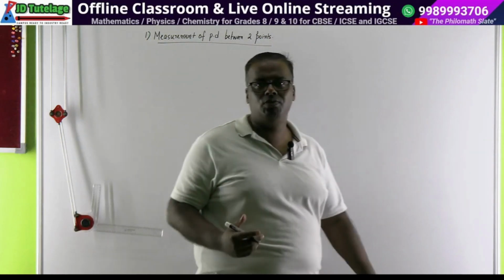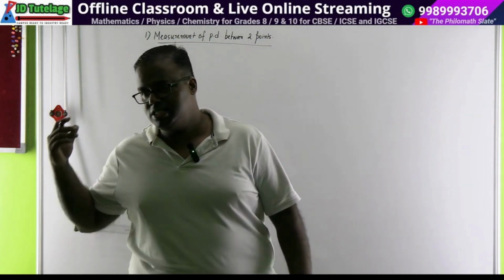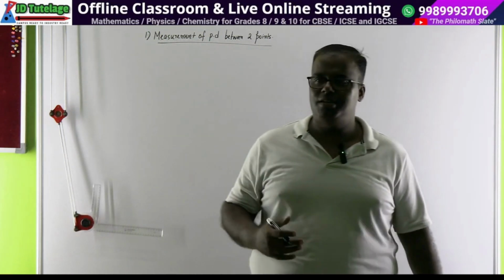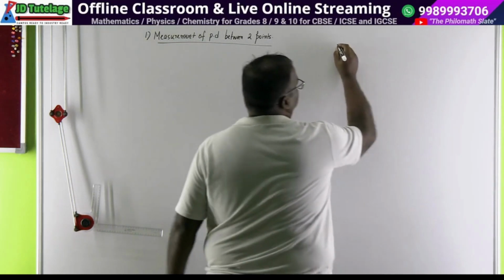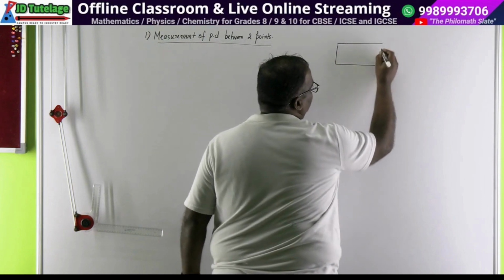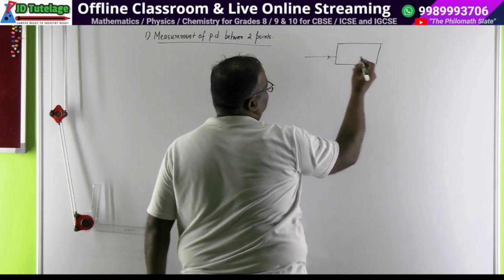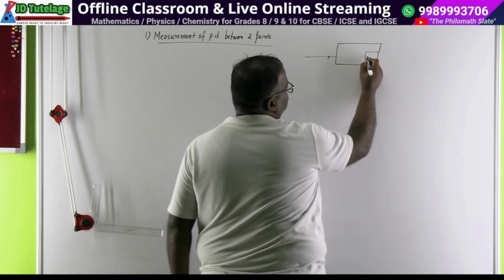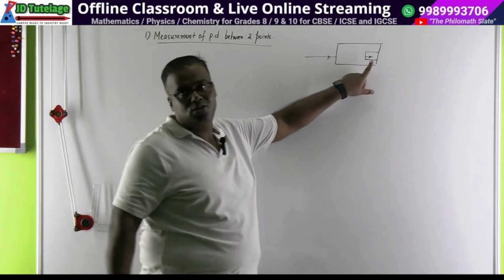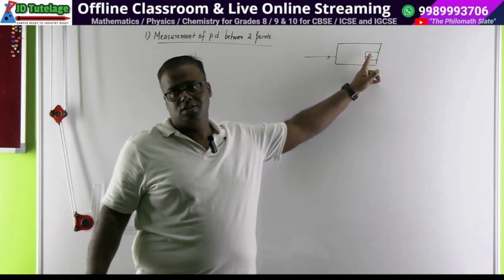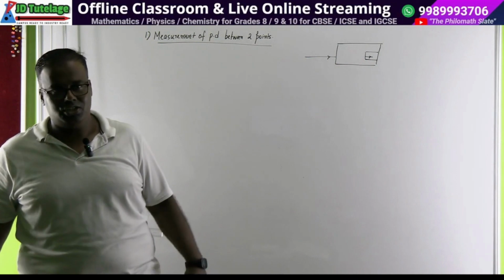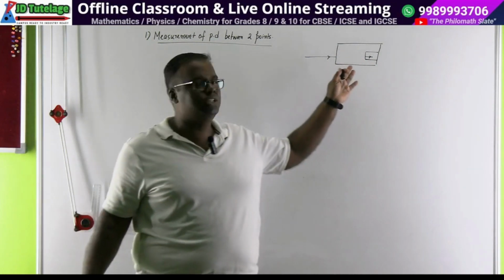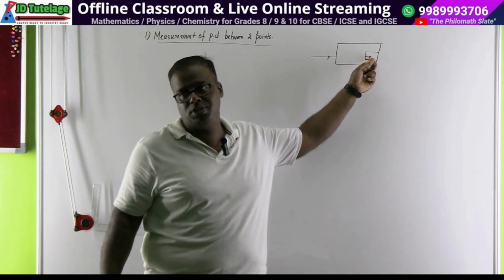If you are a little bit familiar with plumbing, basics of plumbing, understanding these things becomes easy. Let's say this is my apartment, and this is the inlet water line. However, in my guest bathroom, I find that I am not getting enough pressure. What will you do? You'll first go to the other bathrooms, check if the other bathrooms are having good pressure. That means you will conclude that there's some problem in this particular bathroom.